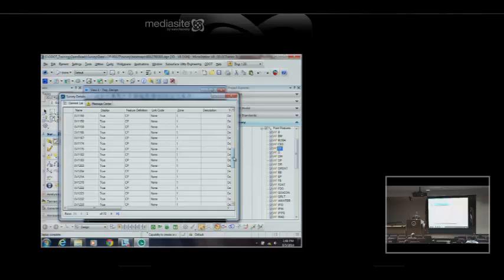They just coded another start, so the previous one ended. So just a quick overview of some of the capability of analyzing and editing data. Now, this was a Trimble DC file, but it was reduced coordinates, so there's no observation data for this one. I've got another one later that is raw data observations that I'll bring up.